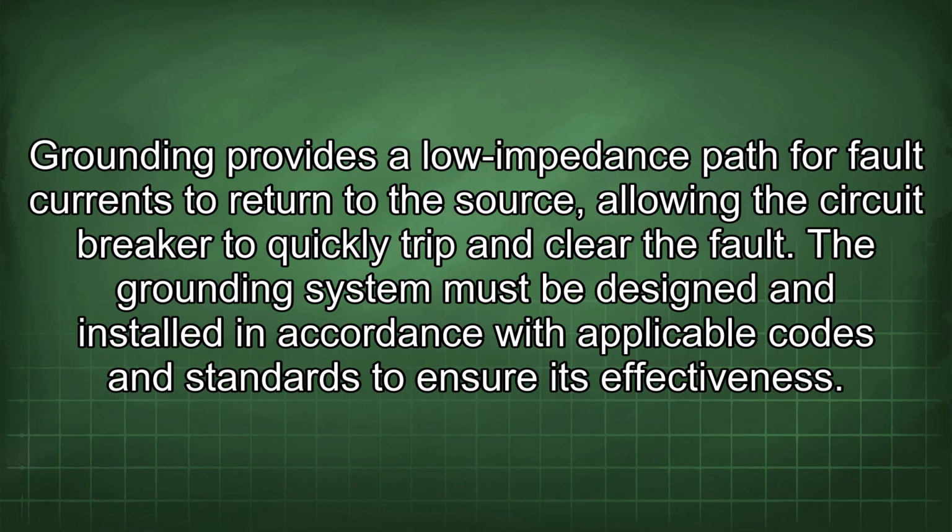Grounding provides a low impedance path for fault currents to return to the source, allowing the circuit breaker to quickly trip and clear the fault. The grounding system must be designed and installed in accordance with applicable codes and standards to ensure its effectiveness.